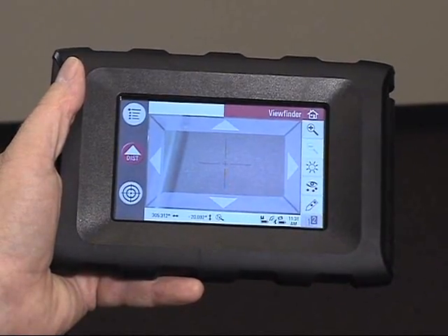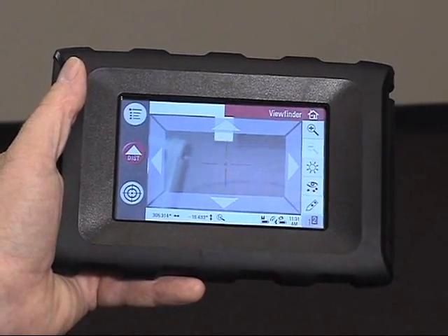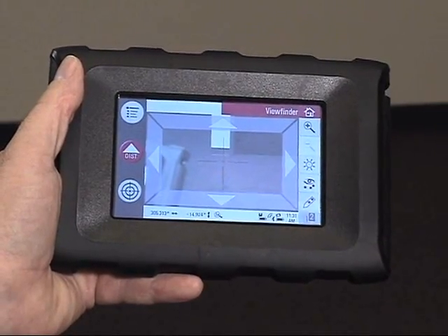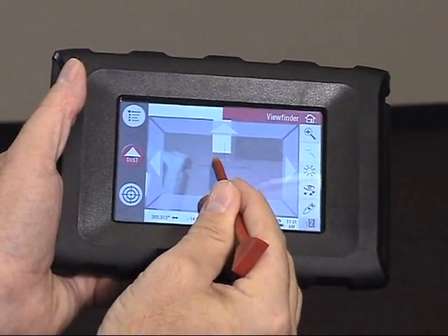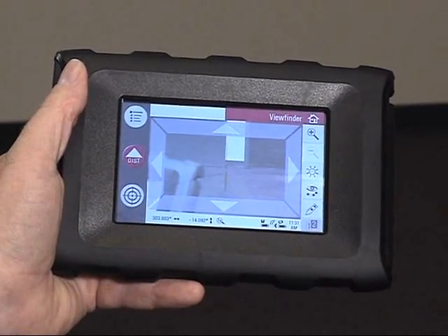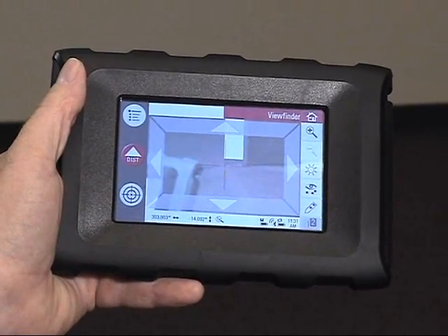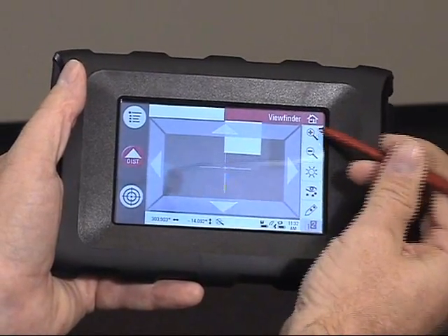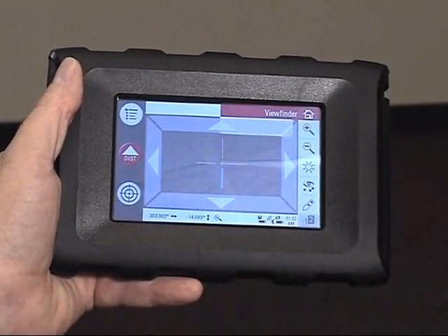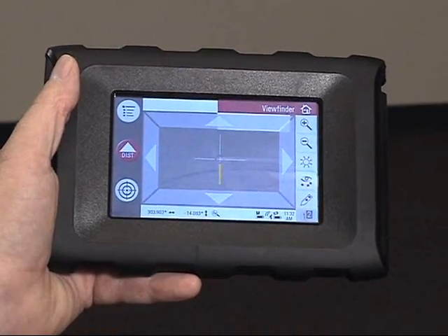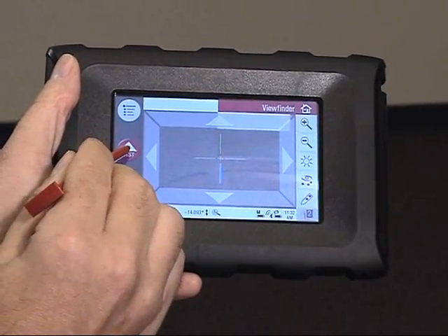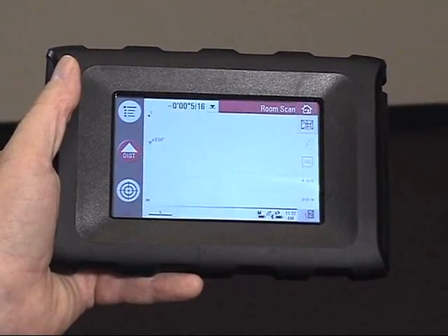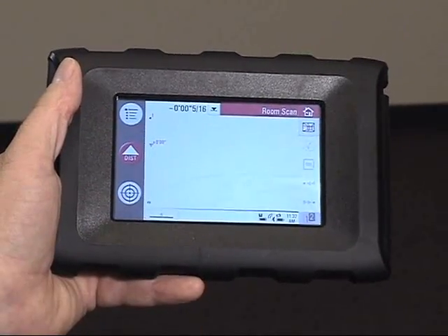Now I'm going to use my hand quickly to come up and just get close by manually moving the 3D Disto. Tap on the screen to get the unit located down at the bottom corner. And if I zoom in on it, you can see we're right down there at the bottom corner. Now we're ready to locate and measure the first position. So we're going to hit the Dist button. And our first point has now come into view.